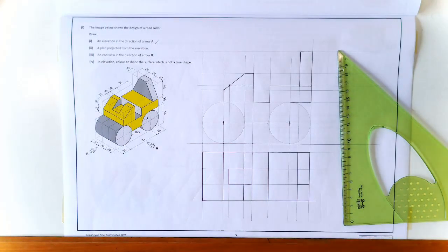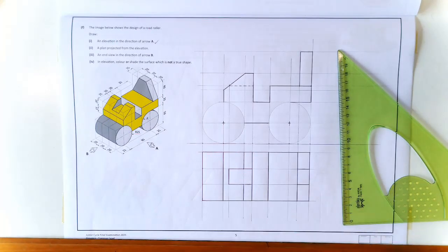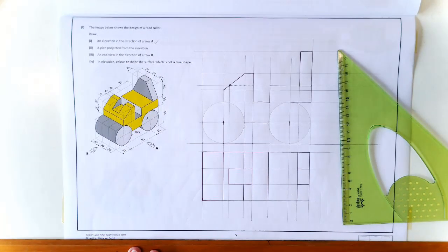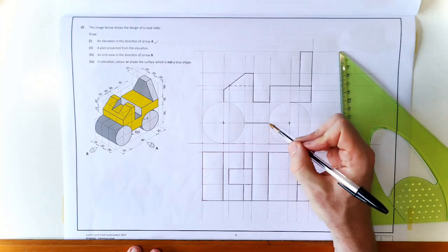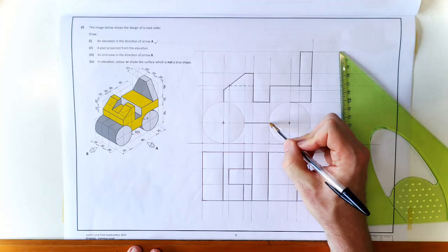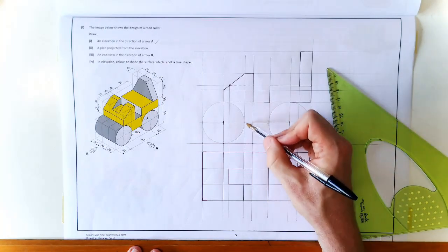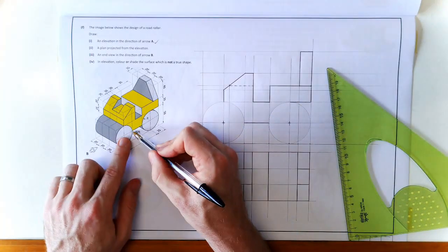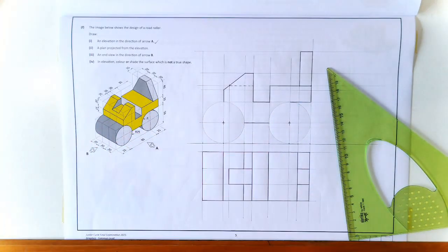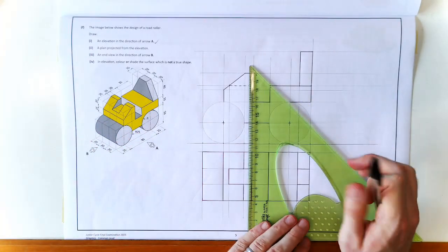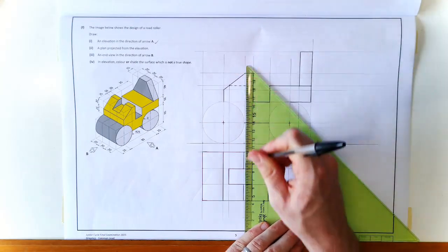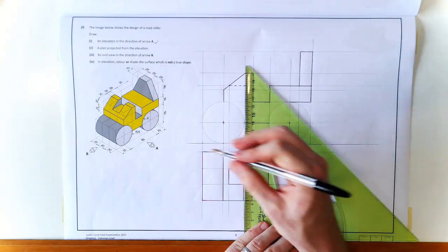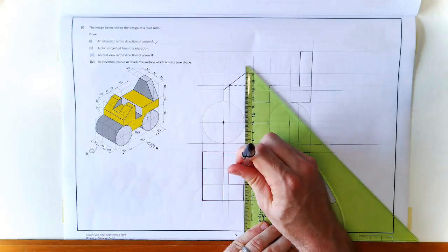Okay. Finally then, yeah, that's all of it. Finally then, before we move on, ask ourselves, is there any hidden detail? And looking at it, the underneath, there's an edge there, but that's actually covered, it's in line. There's an edge there where the cylindrical rollers meet the base, and that is also in line with there, but there's a little section in the middle, right, in here, that's the surface, so we need to show that hidden detail.